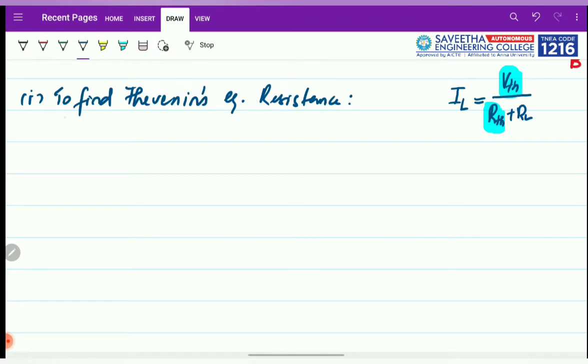Okay, we are going to find this. So for this, coming to this Thevenin equivalent circuit, we need to know some basics on the electrical circuits in order to find out. The first thing in the Thevenin equivalent circuit, if you want to find the resistance in it, you need to remove all these sources. That is, you want to zero all the sources. It means the equivalent resistance is found without the sources.